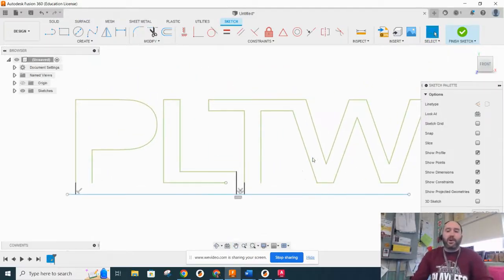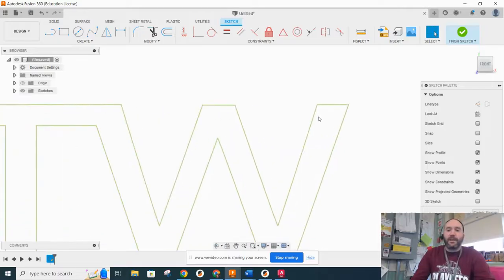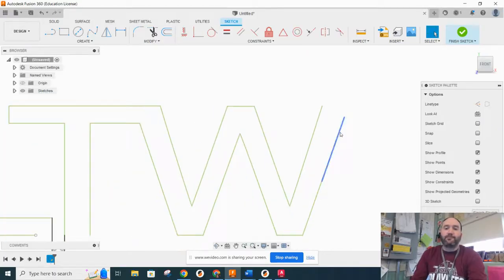Okay, so now we've got to do some repair work on our SVG file. Like I said, these end caps are not going to be very nice to us, especially if we have to come in later to use fillet, we can actually run out of geometry. It can sort of butterfly this and pull it over center. It's not going to be pretty. So I'm going to come in here to our end caps and delete that. This is not enough geometry here, so I'm just going to delete that.